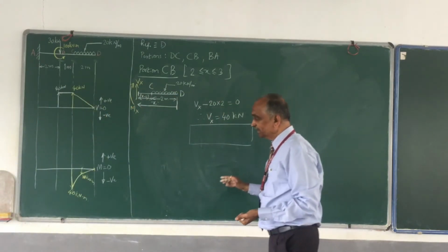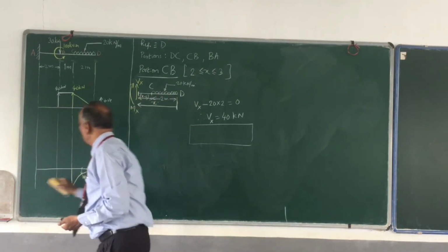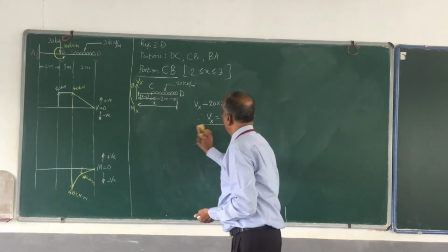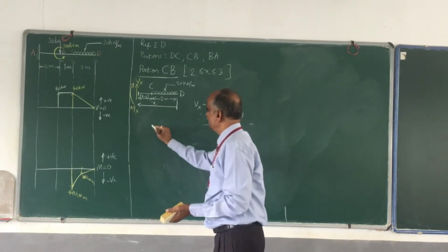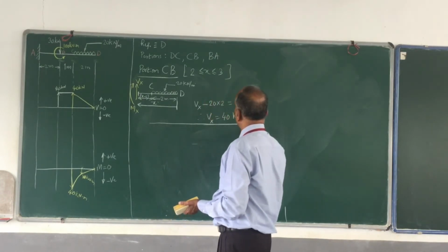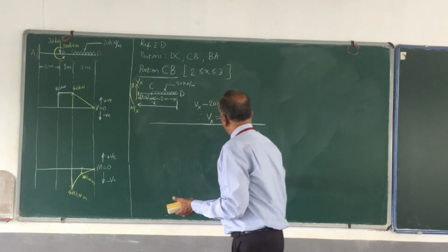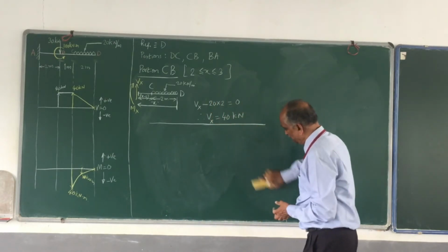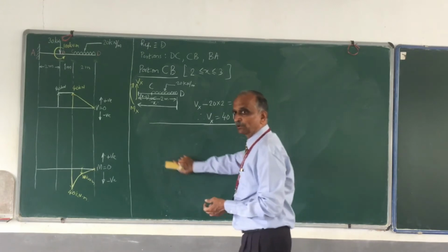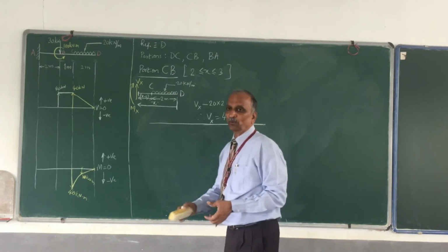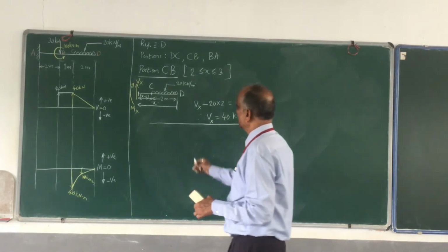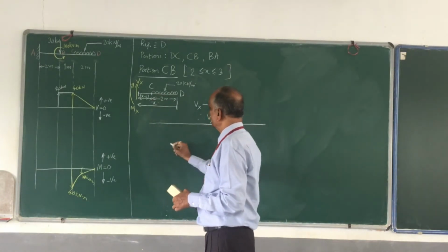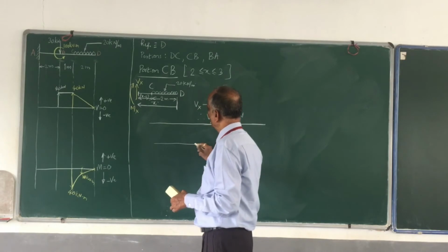I hope it's clear. Then let me go for the bending moment. Whenever you are dealing with bending moment, and if you have UDL, you have to be a little careful. You have to get the equivalent point load for the UDL. For this, I shall draw one more figure. I don't want to have the UDL.